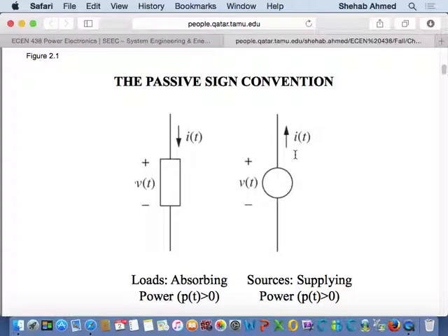Right? Because this is the convention that we used here. For positive current, we use current coming out. For a load, we use the opposite convention for current flow, right? So for a load, we will assume the same voltage polarity, for example, but current will be coming into the positive terminal, and that will be the positive current notation that we will utilize.